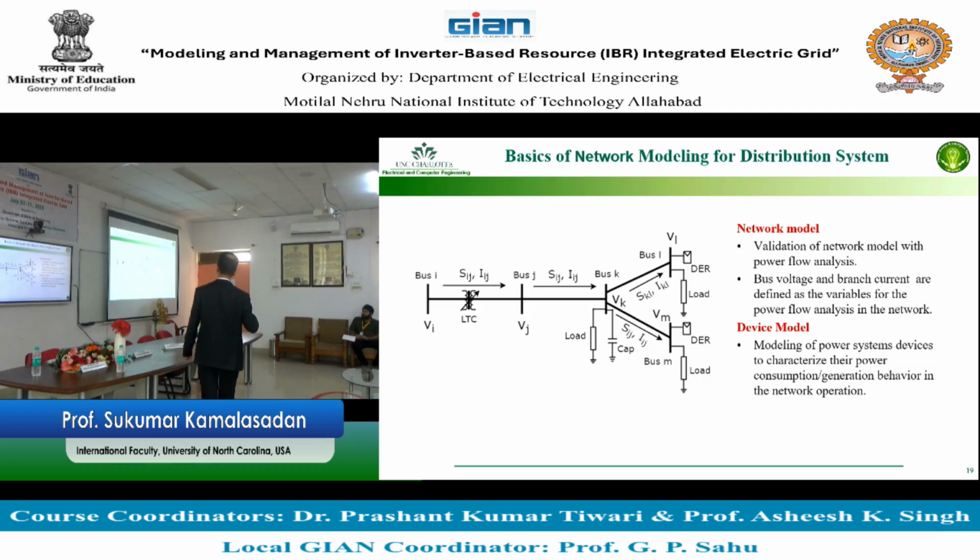We identified two main types of transformers connected on the distribution network that do the job of maintaining the voltage properly. Both are tapped transformers. One is called LTC or OLTC, which taps the transformer to increase or decrease the voltage, looking at the load connected, which is the current of the load.